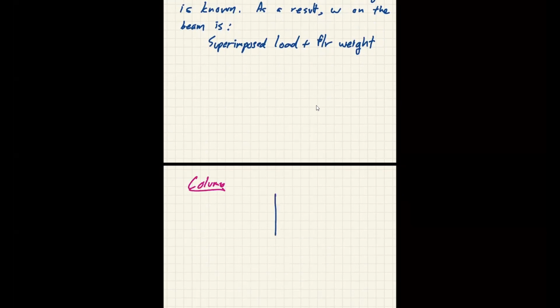This guy will go on to support the roof. Okay. So, and keep in mind that your roof is not a simple beam, you know, that this portion here is a cantilever. You may use the tributary area to summarize the load from the roof.